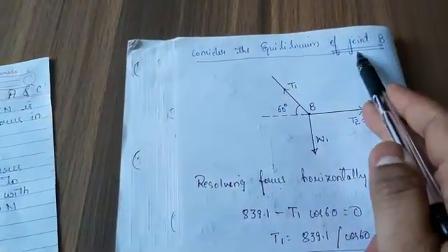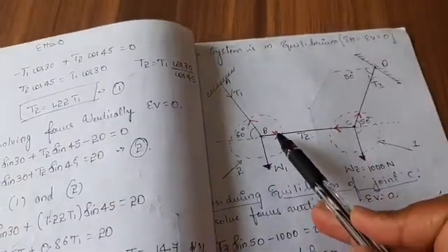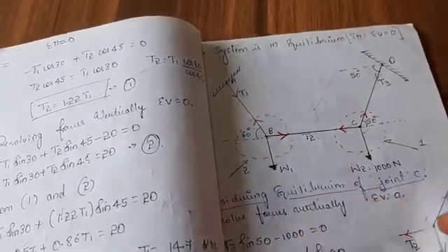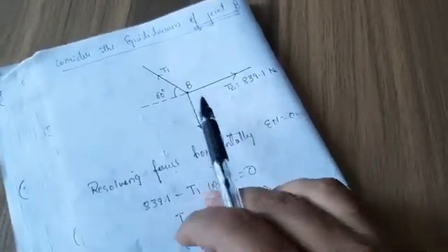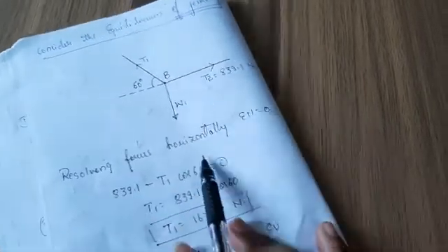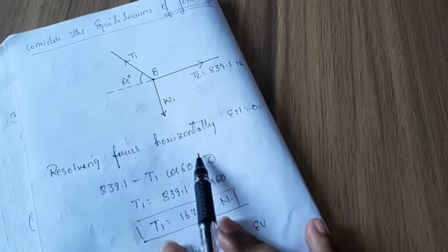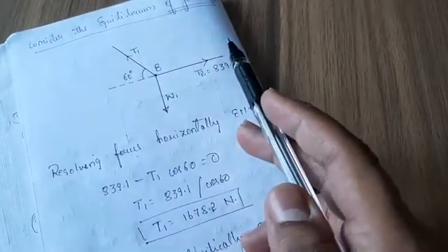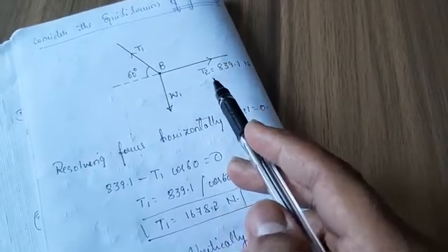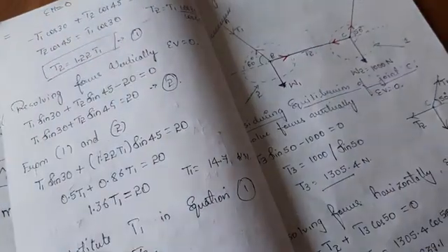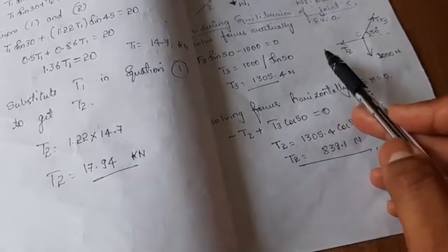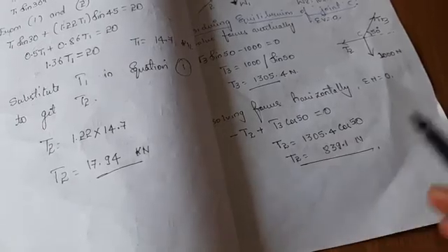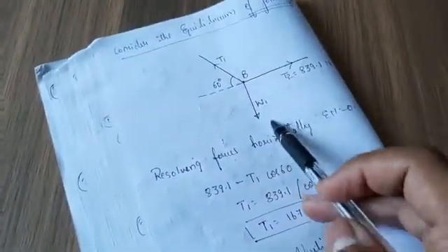Once you do that, you will move to joint B. Now you can see there are three forces here also, so the directions of forces will be like this. You can draw the sketch. Your T2 will be acting in the right direction, because you got T2 as a positive value in the previous steps. T2 is 839.1, which you got as positive, hence you apply the T2 value here to get the further W1.